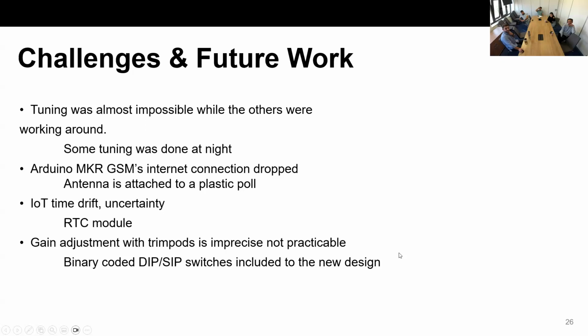The gain adjustment, as I said, we have over 60 dB gain through more than one point. I was using simple trim pots that we all use from our board, the ones that we simply adjust with flat screwdrivers. That was fine here in the UK. But even twisting them with the screwdriver and probing them, estimating or calculating the gain became a huge pain.